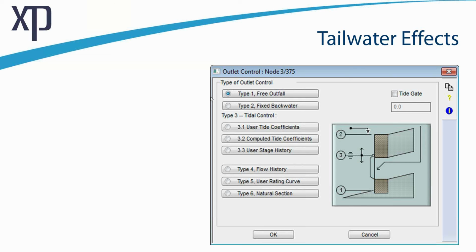I would try and build into my hydraulic model some additional overland flow away from the pipe network itself to allow space for any influence that the outfall has to occur within the open channel itself, rather than potentially affecting the pipe system, because you could falsely undersize a pipe or a culvert in that kind of arrangement.